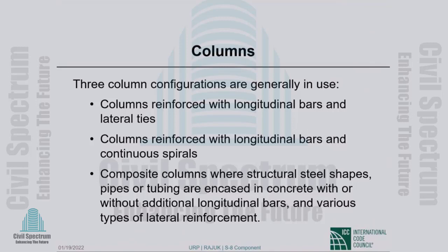Three column configurations are generally in use. Now, in my opinion, the first two are the main ones; the third one is not very common. Anyway, the first is columns reinforced with longitudinal bars and lateral ties. Those are by far the most common.